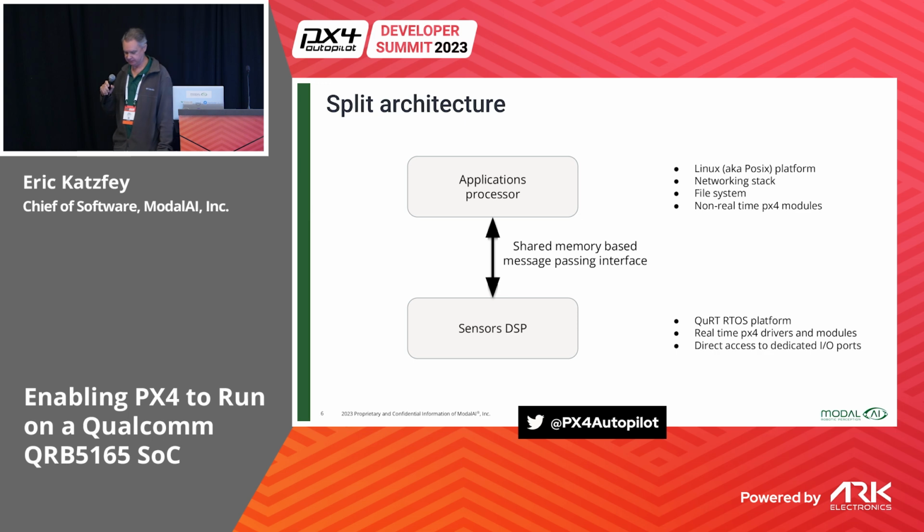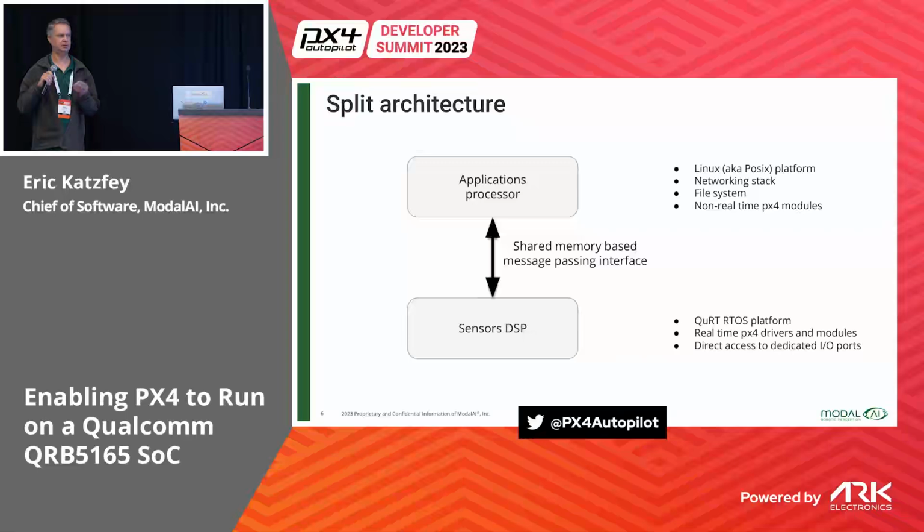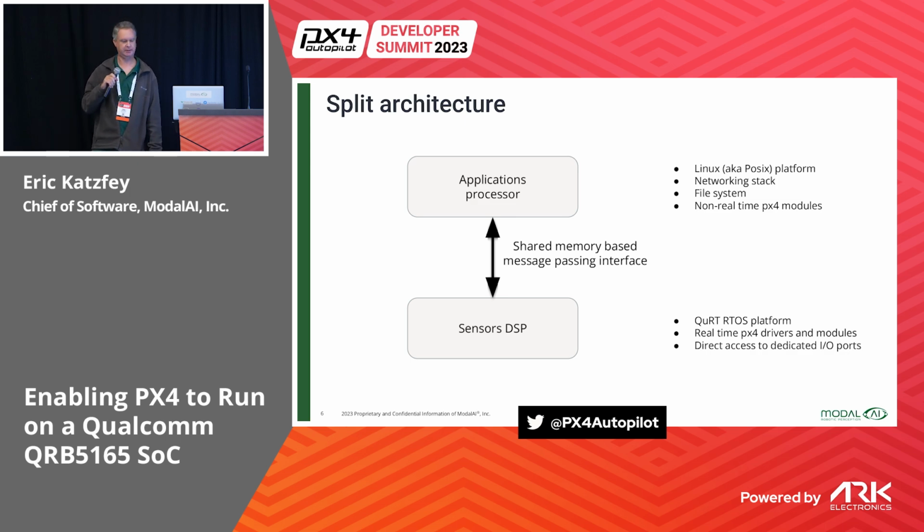One of the really unique things, if you look at the PX4 architecture, is that it's not NuttX RTOS running on a microcontroller. This is quite a bit different environment than that, not just hardware-wise, it's not a microcontroller, and not just RTOS-wise. This is one of the main differences right here: we've actually split PX4 across two different processors. The applications processor, that's what we call sort of the Linux, this 8-core, where we're running the Linux.